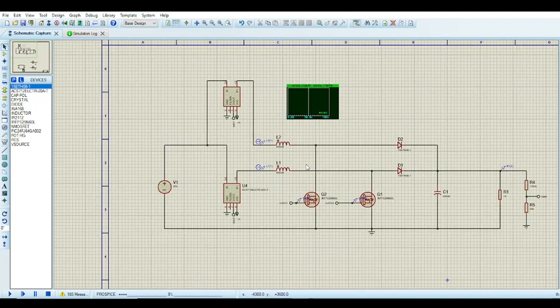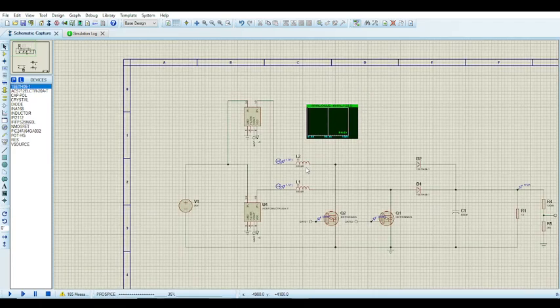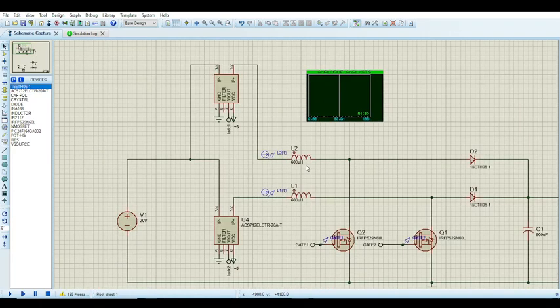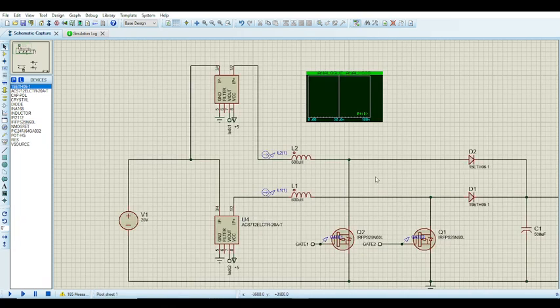And also, for this particular inductor, this is unrelated to the code actually, just in terms of hardware. I've seen it used before, where these two are coupled to sort of save hardware space. But the coupled inductor also has a downside. Depending on how you construct it, if you use an E-core, then there's a risk of leakage inductance, where at that point you have to take care of the MOSFETs and design a snubber for them, because of the leakage coming out of the coupled inductor.